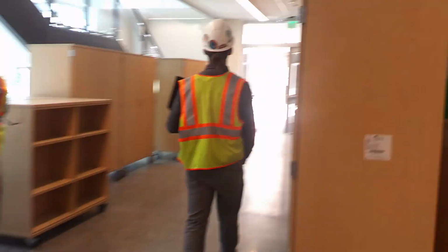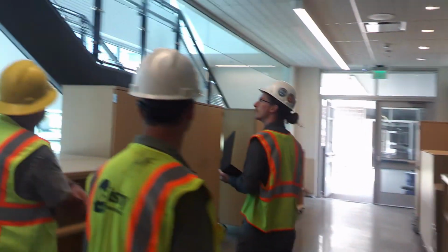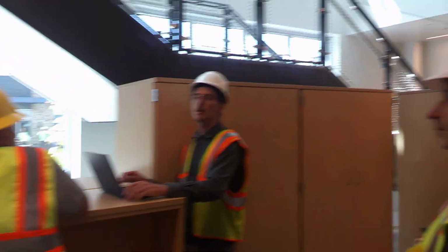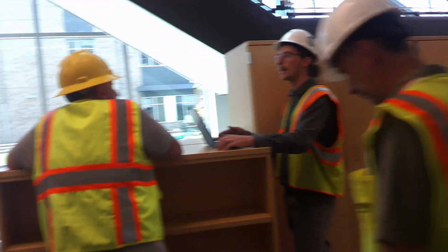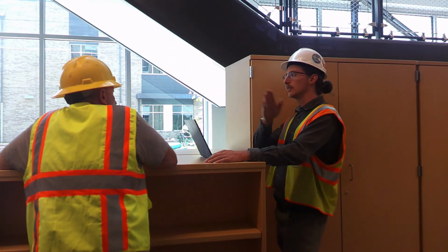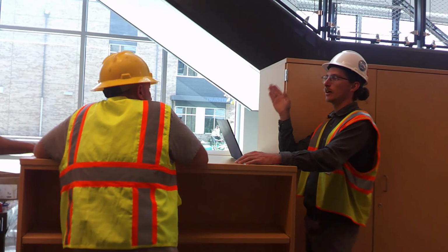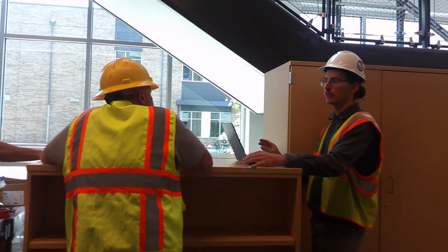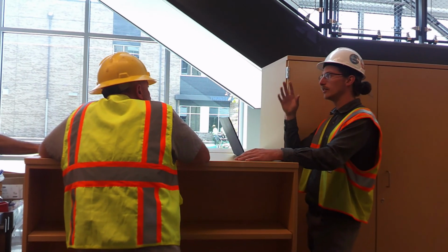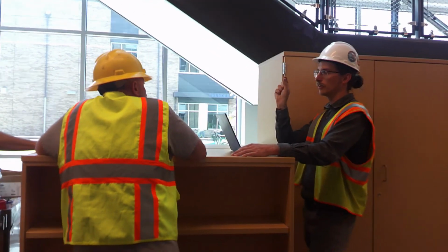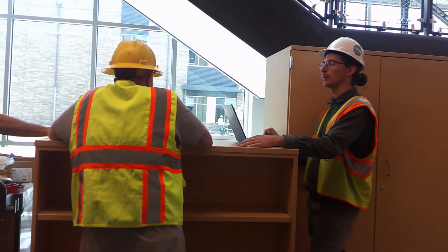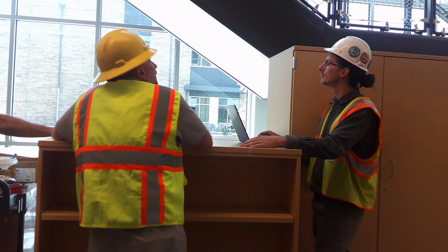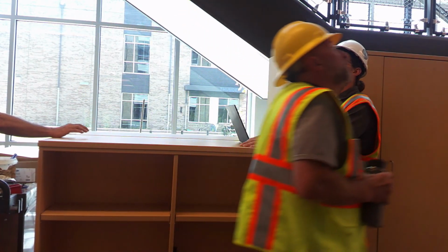Let's see. Oh, and also on dimming, just about everywhere in the building, all the trim on all the dimmers is set to 9 out of 10 volts. So on the dimmer, when it says 100, it's actually at 90. That's so that 10 years down the road, or however long, when the LEDs start to wear out, you'll have that little extra boost to bring them back up.